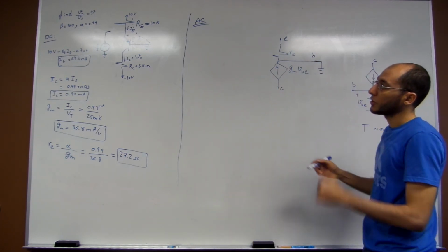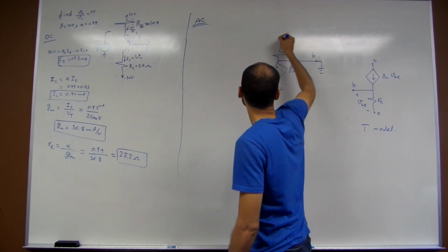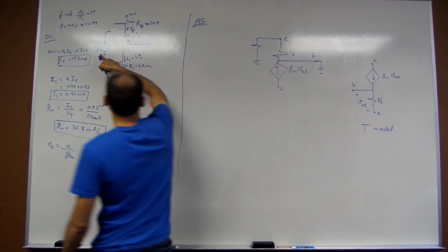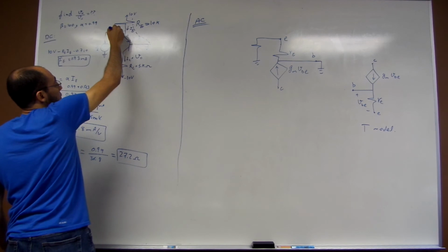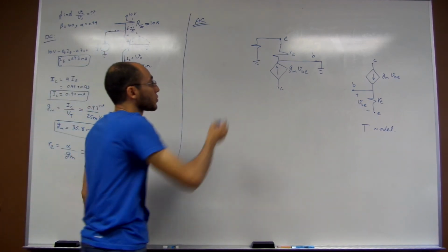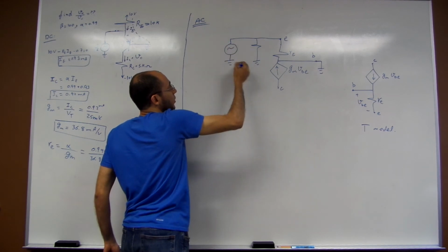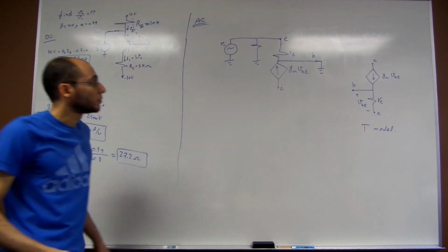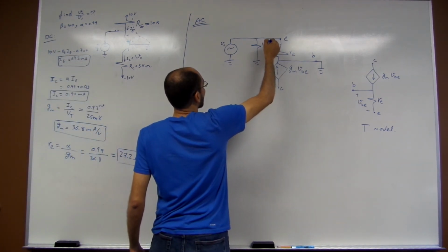The emitter has a resistor passing to the ground, and then the input, which is connected here because there was a capacitor. There was a capacitor here, and the capacitor is a short circuit. So you end up with the input from the emitter to the ground. Okay, and the value of this is 10 kilo ohms.